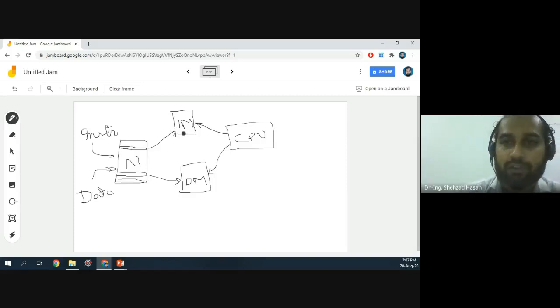All the instructions go to this memory, and all the data elements go to this memory. And if that is the case, you can then have both these operations simultaneously. Now the only problem left is, how am I going to populate instructions in the instruction memory and data in the data memory?